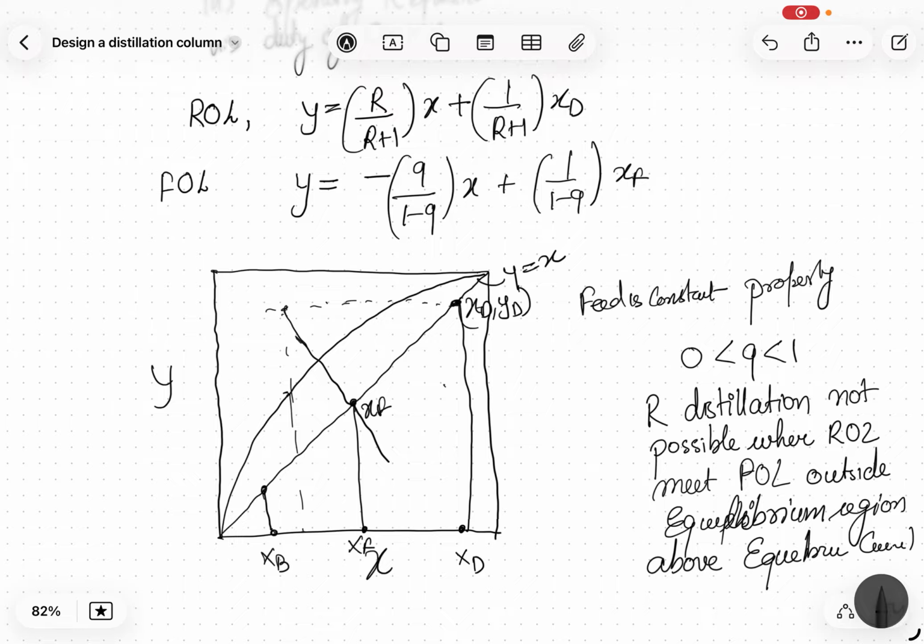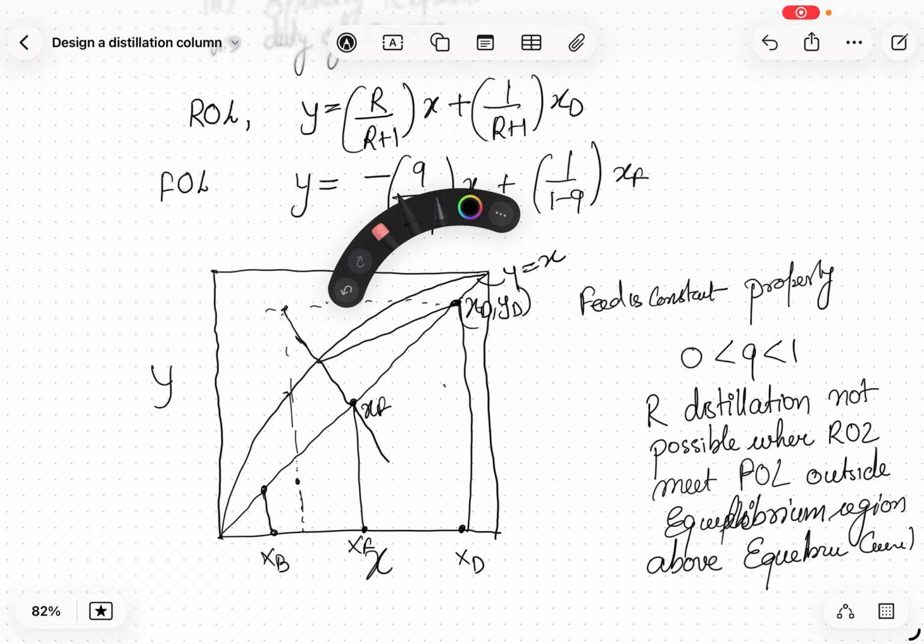You are fixing the amount of X in the mixture and then you cross such that you get more B compared to X in the mixture. Because you have this XB, and you are fixing the XB, you start heating, and the amount of X in the mixture will start going up. This line represents that as you are heating, at every heating the mole fraction of the vapor will change. But it is not going to cross the equilibrium point.